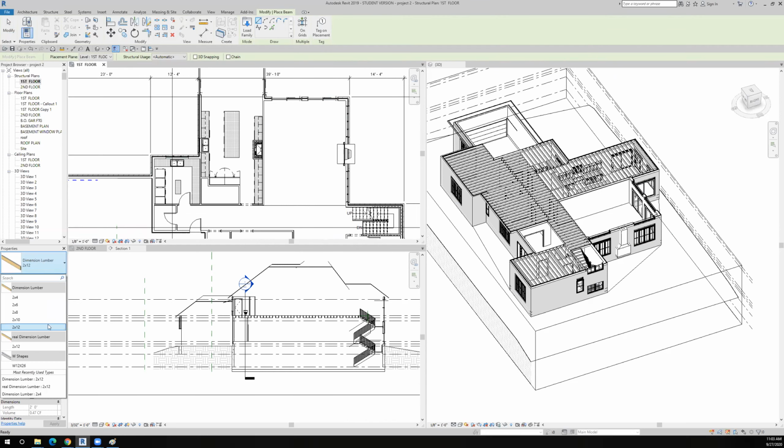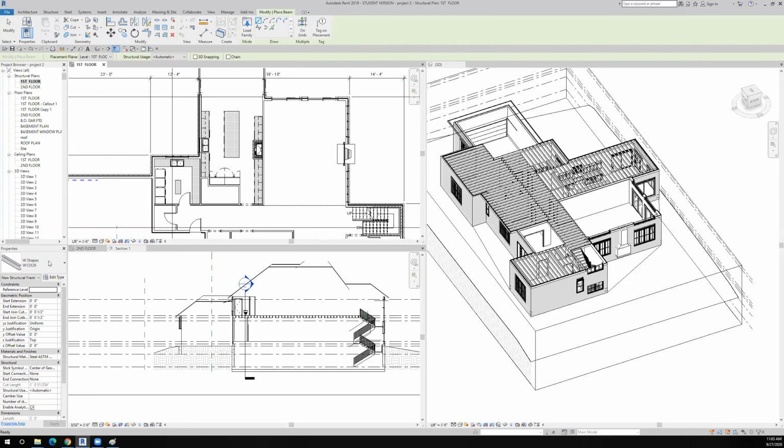And I believe Revit gives us a steel beam. Of course, if this were a real project, we would calculate the loads to determine what size beam we wanted, but we have a steel beam and then we can use that. So I'm going to click here and I'm telling Revit that I want to put in a W-shaped steel beam, but it wants to know what the reference level is, and I'm going to say top of steel beam.